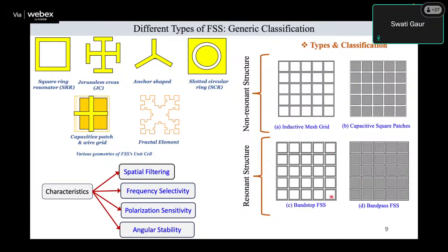Okay, sir. So in FSS design, there is no thumb rule or any specific formula for the spacing between two elements? No, it is not an antenna array. You should basically treat the FSS in terms of periodicity, the way I defined.